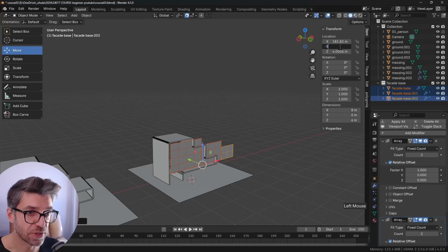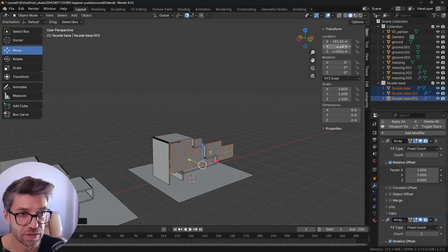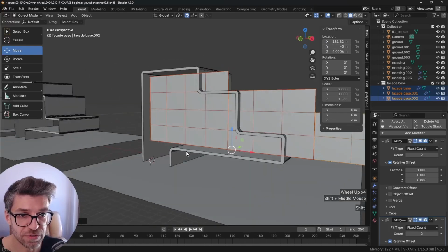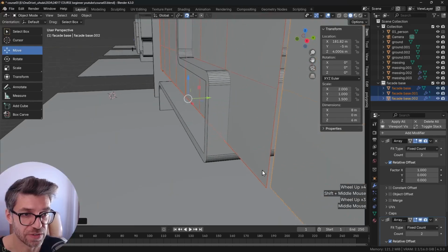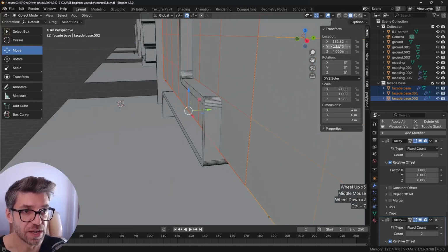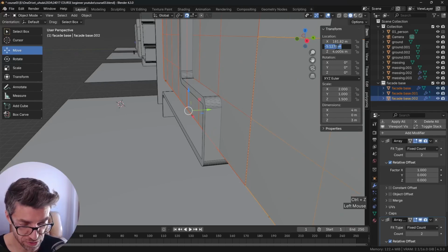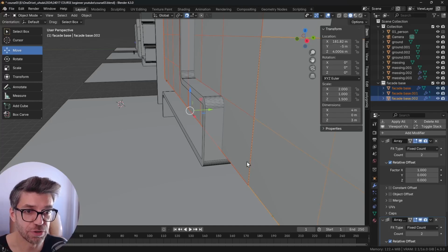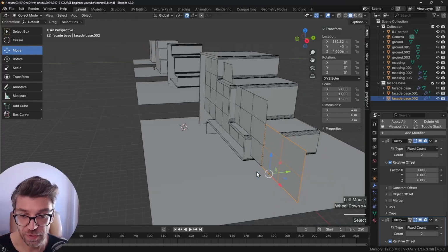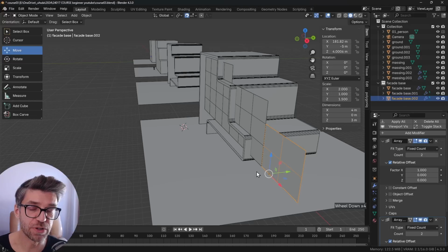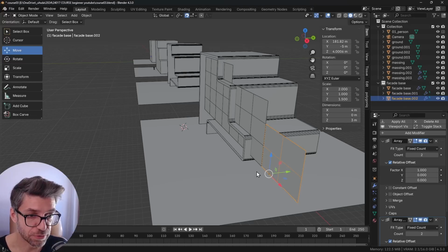And because we're dealing with a lot of objects, now if I click enter, what does it do? It should have just moved 1, and you can see here there's a slight difference. And if you want to move all of them, let's click on minus 5 and then Alt and enter, and now that's going to move all of them. And this here, 4.0006, sometimes Blender doesn't compute the right number because it doesn't work with doubles, it just works with float numbers. Can't really tell you exactly what the difference is.